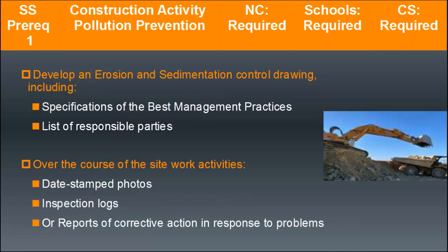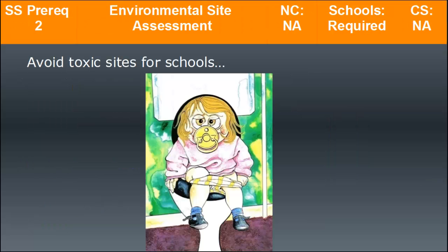You also need to develop an erosion and sedimentation control drawing that includes specifications of the best management practices and a list of responsible parties. Over the course of the site work activities, you'll need, once again, the date stamped photos, inspection logs, or reports of corrective action in response to problems. So once again, not just listing problems, but also how you are going to correct those problems.